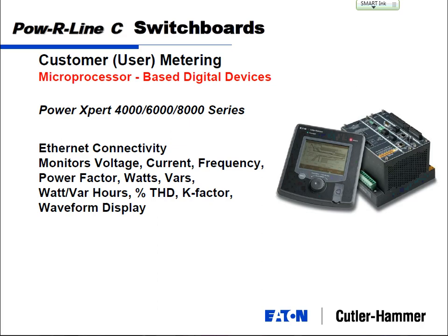Todd, I don't know if you know, in 2014 there's a major change where they will allow you to size the lighting system based on the energy code, not based on the electricity code, if you can prove that your lighting system is what you say it is. That might come in handy. For example, for a commercial building, we use 3.5 volt-amps per square foot to size the lighting load. If you're using LEDs, you can get away with 1 volt-amp or less per square foot to meet the energy code. But why do we need a bigger panel then?